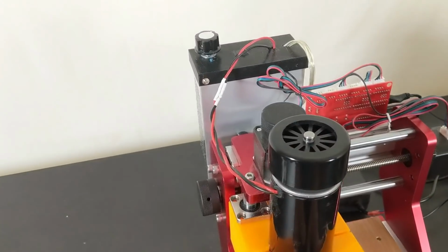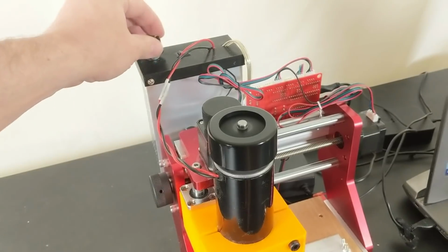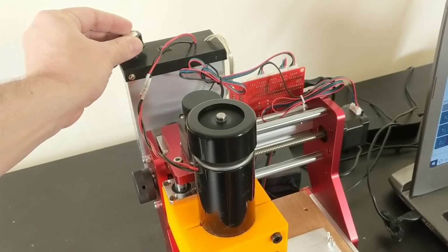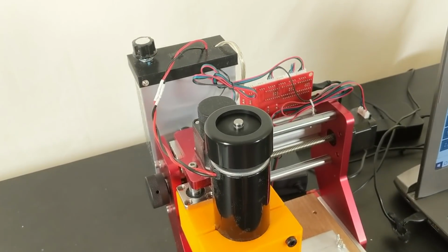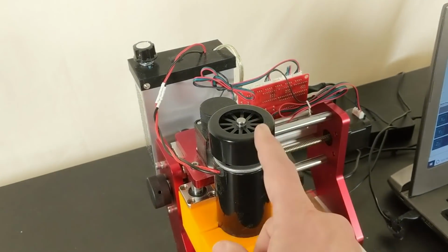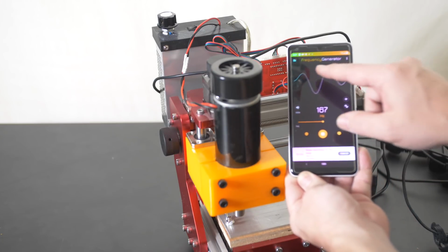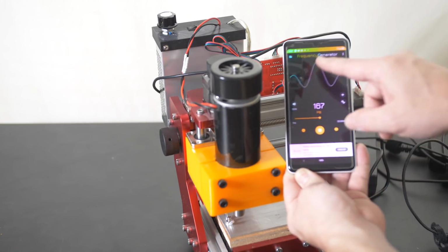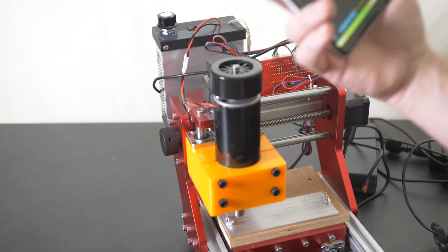Now, we have a small problem because this motor apparently maxes out at 12,000 RPMs, up there. But most of the feeds and speeds that other people are using on the internet are down around 10,000 RPMs. So I'd really like to know how fast this motor's going. And there is a trick to that we can do right now. Here on my phone, I've got this frequency generator running. I can just stop it and start it, but it's playing a low note at 167 hertz. And if I put this to the microphone, you can hear what that sounds like.